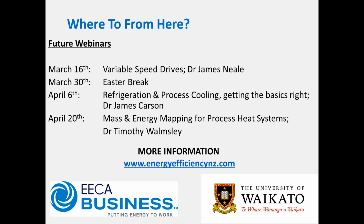Normally, the reason for that is that when you buy an automatic blowdown valve, like say a Spirax Sarco type unit, it comes with the conductivity unit built into it, right? That's the module, and most of them are supplied by RCR and things like that. Dissolved oxygen is less common, but it is still pretty common, either via a permanently installed online meter, or some sites might, say, have multiple boilers, and they'll purchase a portable unit that can be connected up for deaerator testing.